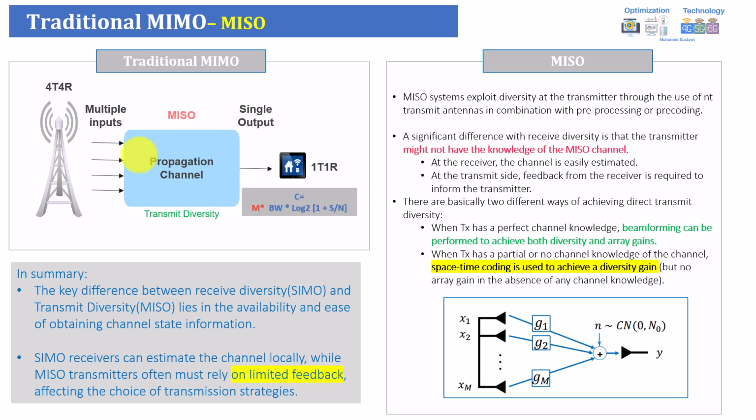But not the opposite way around. For example, the transmitter does the sending but doesn't have any knowledge about the propagation channel. So he will do the transmission from different directions or whatever, but he doesn't have knowledge unless he requests it and receives feedback about the radio condition, usually something like PMI, CQI, rank, and so on. But in the normal scenario, he doesn't have any knowledge. So whenever he transmits, he's blind. He doesn't know what's happening in the propagation channel.